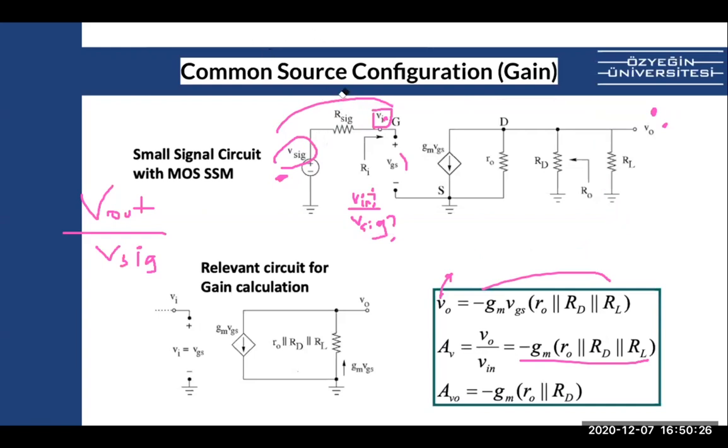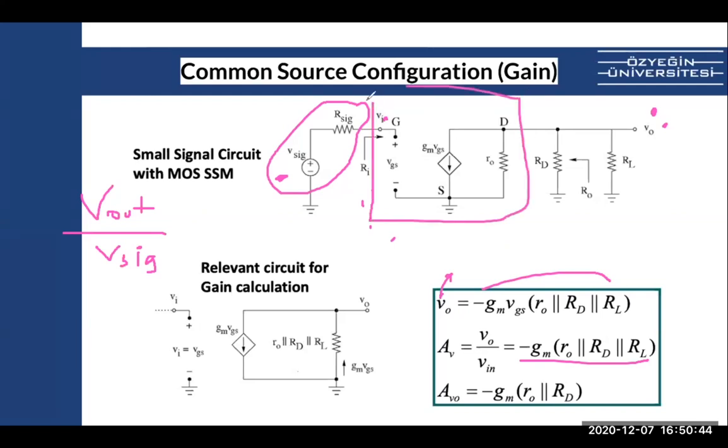It's not really a black box. This is connected to, let's say, a source analyzer or a source generator, so sometimes you won't be able to measure it directly. But the intrinsic gain is the gain of this transistor alone, where we multiply gm VGS with ro, remember, and we found the gain gm ro.